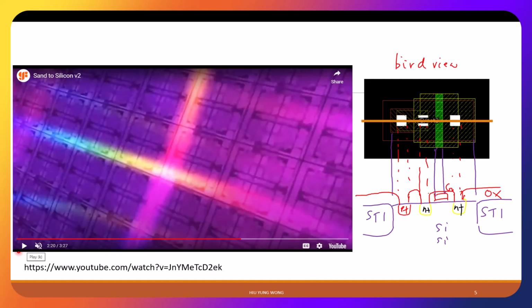Copper has very low resistivity, but it cannot be manufactured using the traditional aluminum method. So you cannot etch it. In the past, you deposit the metal and then you form the photoresist, and you etch those you don't want, right? You use some chemical reaction to remove them. But copper doesn't work. You don't have such chemistry that does it effectively. But what they do is use the dual damascene process. You electroplate the whole wafer with copper, and then you CMP.